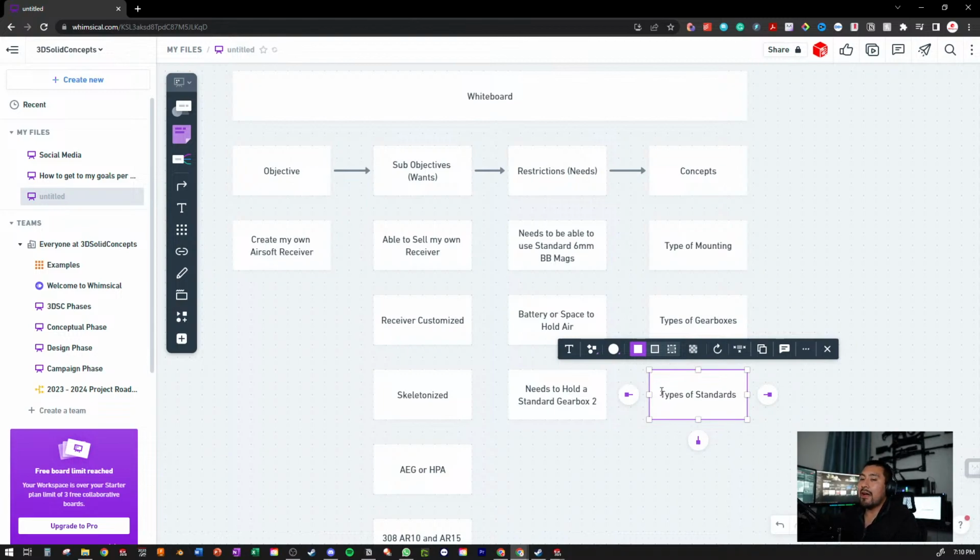Now, one thing I hear out there a lot, and to be honest, I didn't really understand why they kept saying this, but what I mean by types of standards, for example, American standards use a 1/4"-20 screw, or if you use in-house, you use an M3 screw, etc. So that's the type of standards I'm talking about. Dimensional standards. Where I work, we have a standard length and width of hole bolts that go for our seats. But here, for example, I'm talking about mil specs. I hear that a lot, and I'll be honest, I didn't really understand what that meant.